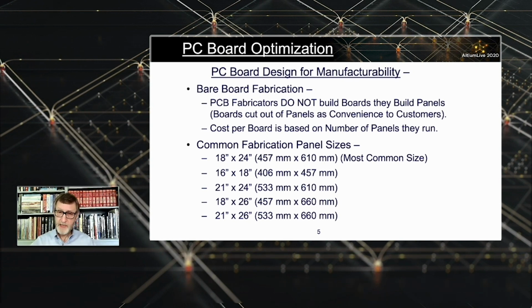Before you design your next project, you should find out all of the panels that all of your suppliers can produce with, and pick a panel size or panel sizes that is common to all of your suppliers, so that you can pick board sizes, and I'm going to tell you in a minute how to do this, that panelize well for producibility. If you want to minimize cost and minimize scrap and minimize what you pay for boards,